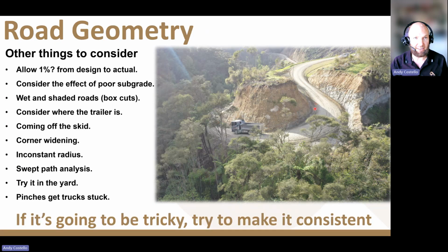A whole bunch of other things to consider with road geometry. All of these things will impact how steep you can go. I'm not going to cover them all today. We don't have enough time. I'll leave them up there in case people want to review the slides later. The comment I will make is that if the road's going to be tricky for any of these reasons, then try to make it consistently tricky. Trucks get stuck on pinches. If you don't have pinches, there's a better chance of the truck getting out, even if it is consistently tricky.